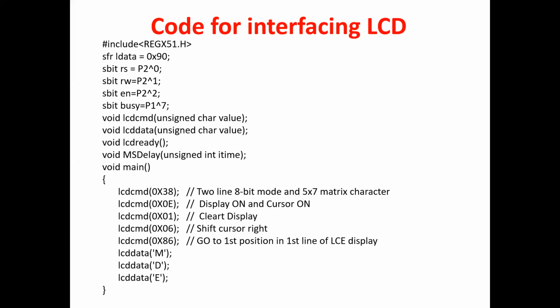Before sending data, we need to verify whether our LCD is ready or not. Once we have placed the data on the data pins, the LCD takes some time to latch the data into its internal registers. Meanwhile, it will be busy. So there are two approaches here. We can provide a fixed delay after placing the data, or we can wait until the LCD indicates that it is free or busy. If we use this LCD ready function, we use the LCD's time efficiently. And for delay, we are using the standard delay program.